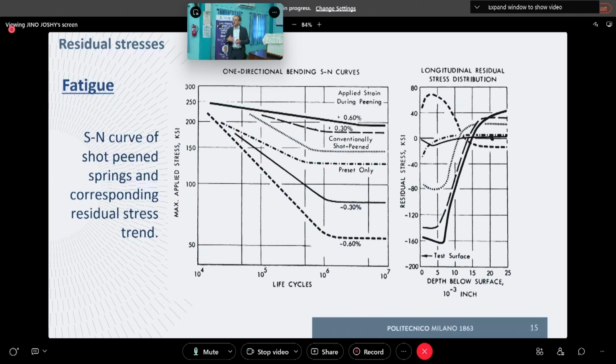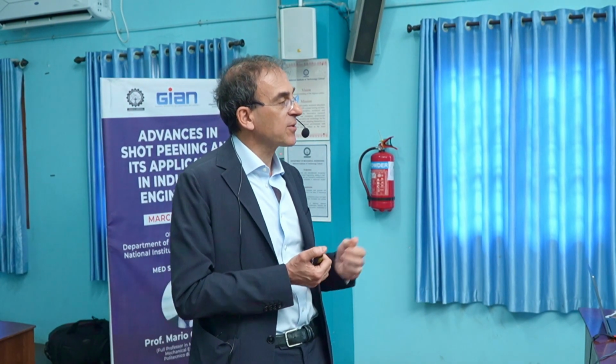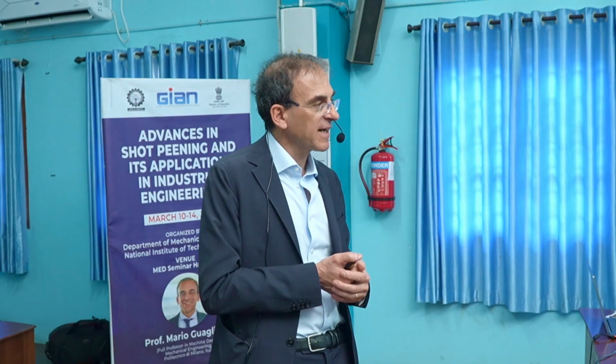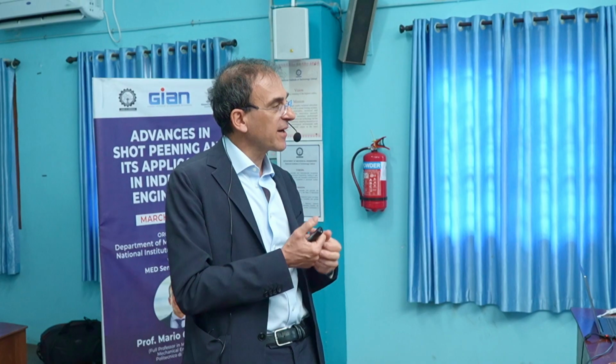So we notice the effect of residual stresses induced by shot peening. And then what can we see? If we apply shot peening with preset, we are applying what I called in the first part of the lecture this morning stress peening, that is shot peening while at the same time applying a mechanical load.